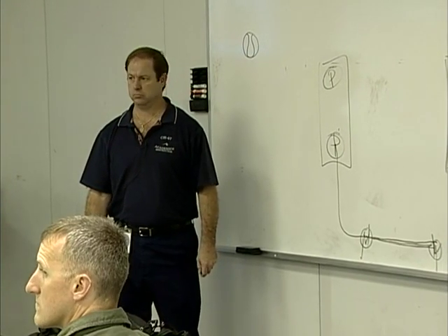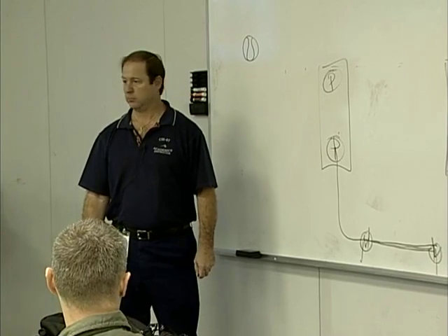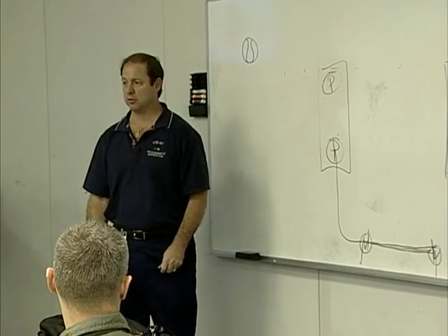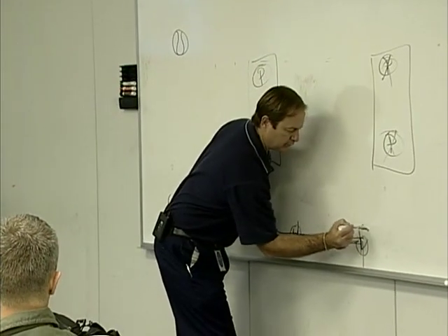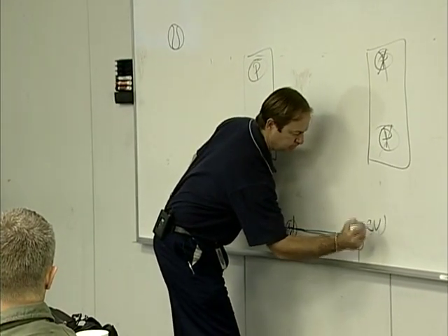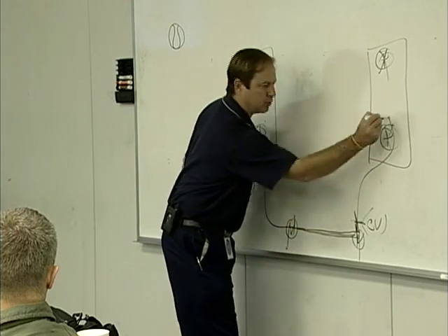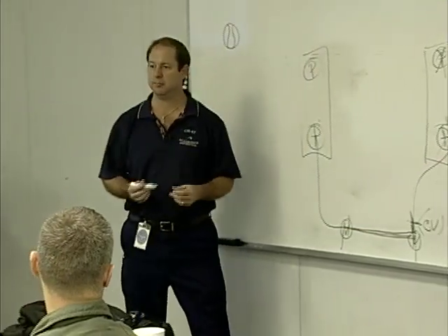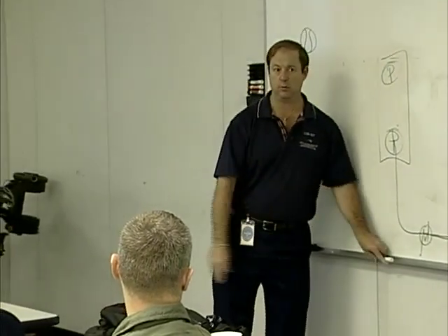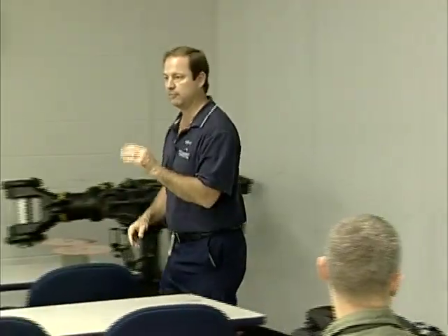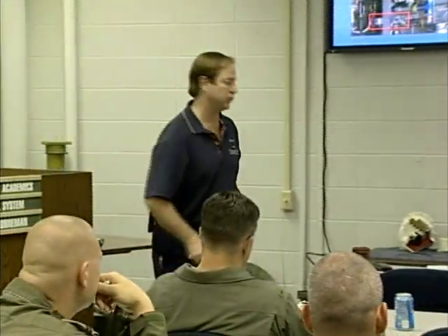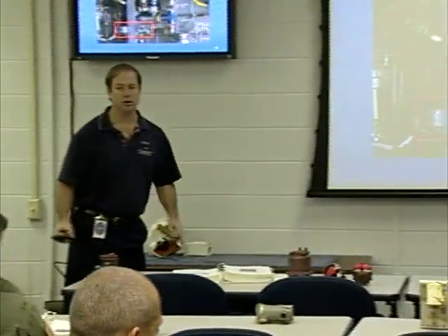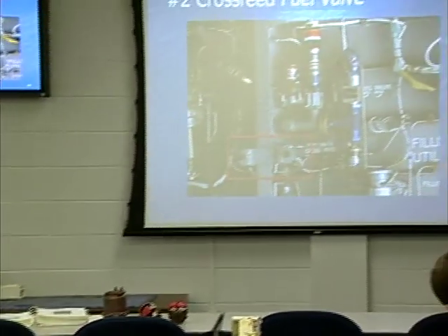Can it go backwards to the other tank? No. There's a one-way check valve we're going to talk about here in just a second. Back here in the system, there's a check valve that prevents fuel from being able to go back into the tank. Good point. Okay, good job. Nope, there's no need to. There's a one-way check valve. Good point. We're going to get to it, actually. We're going to show you the check valve. That's why I'm trying to be very careful. The check valve comes out, actually.